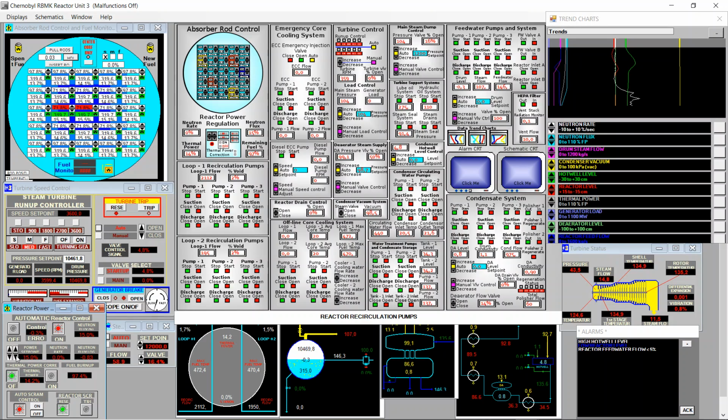So now I will go a bit lower once we approach the pressure we need in the turbine to do the synchronizing at the reactor power that it's supposed to be. Okay, we're at 10% of reactor power again. The pressure set point in the turbine is 11,000. At 11,500 we can already synchronize.